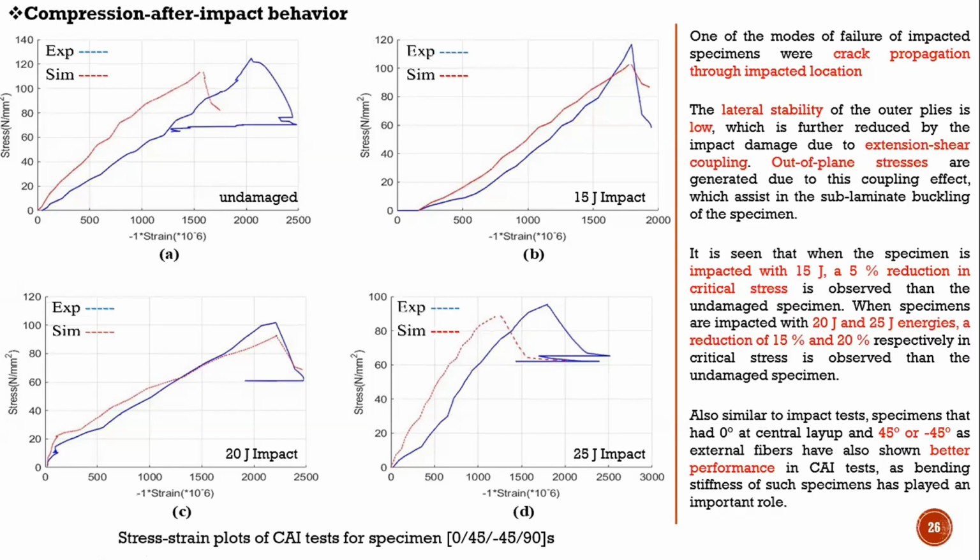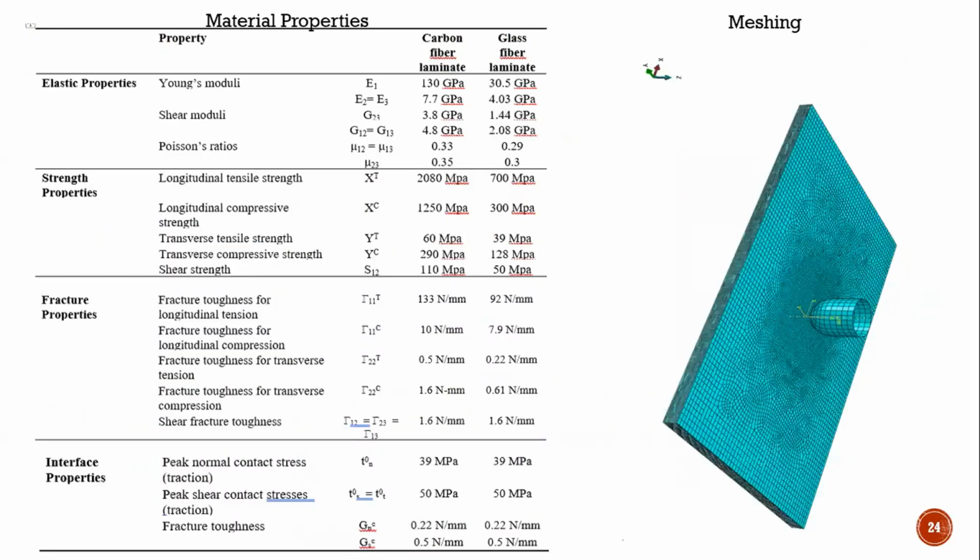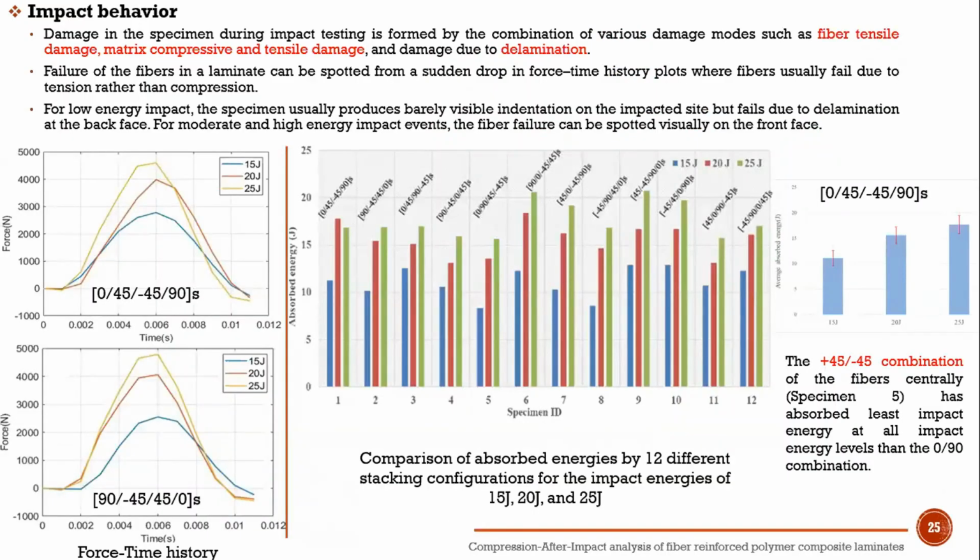This is a cylindrical problem, so you just need a representative volume element, with a volume of matrix and a volume of a single fiber, and then you load that single fiber at one end. Then you need to give interfacial properties, like I've shown here. Some interfacial properties will be there, and you can simulate that fiber pull out test in ANSYS, or you can do it in Abaqus as well.